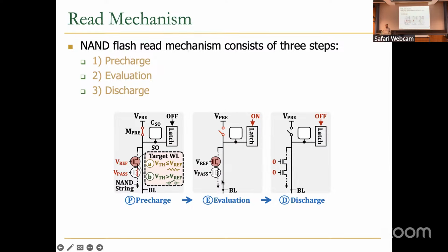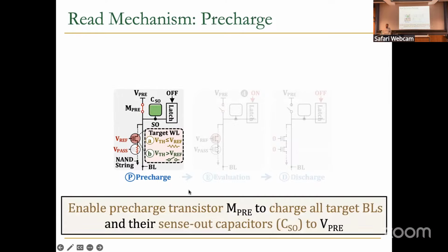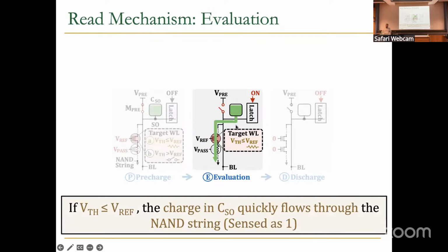And now, essentially, the bit line is connected to this string. So if that string is on, then we can actually evaluate if this charge is discharging or not. Okay. So there's a sensing circuitry here that I will explain in a bit. But in this picture, I'm kind of ignoring it. But with that, you can understand that.